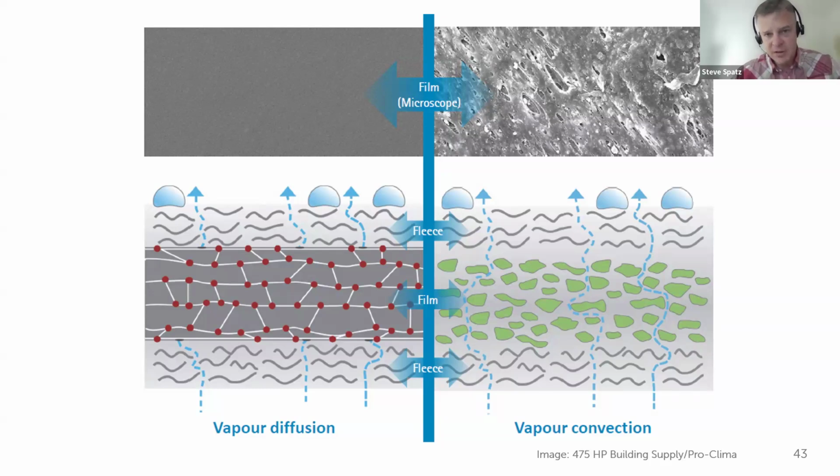So those types of products are dependent on a level of pressure differential between inside and outside to allow that vapor transport to occur. Again, we're getting very airtight building assemblies now and very good air barriers, so there's little pressure between inside and outside now. So it retards the capacity of vapor transport through that type of product, versus other products available on the market now from manufacturers where it's an actual engineered film that does not rely on pressure differential for diffusion to occur through it.